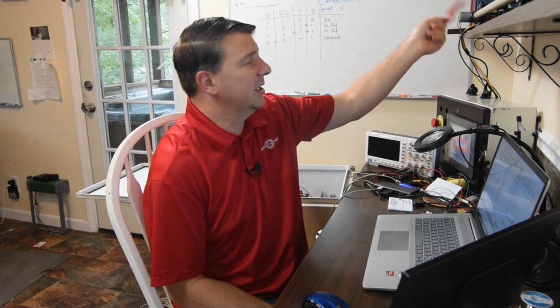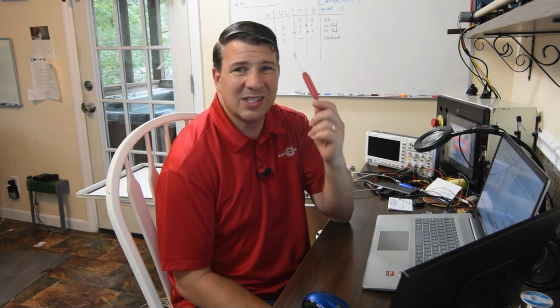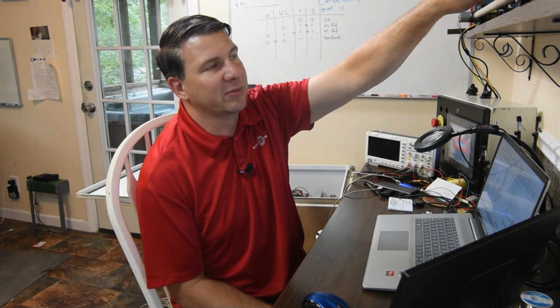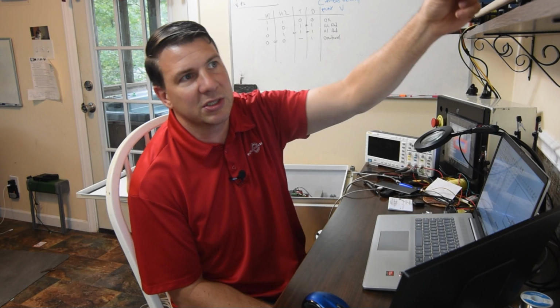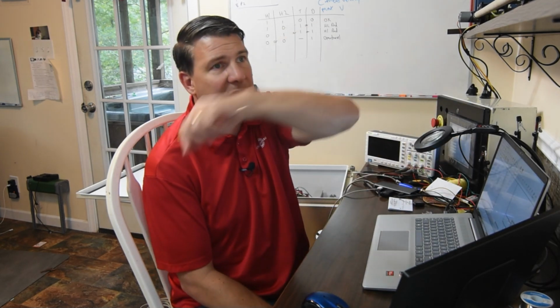That's a great question. Why would we want to return to home? Well, it may be an error. We may not be all the way past it. If we are all the way past it, the launch went all the way, and that cart's gone anyway. All right, so we'll worry about that in a second. So if it's not gone, the cart may still be sitting right here. We're just going to slowly move it back into the home position and deal with it that way. So that's kind of a fail-safe as well. So we're going to go ahead and clear that, and then it's going to return and set itself back up.